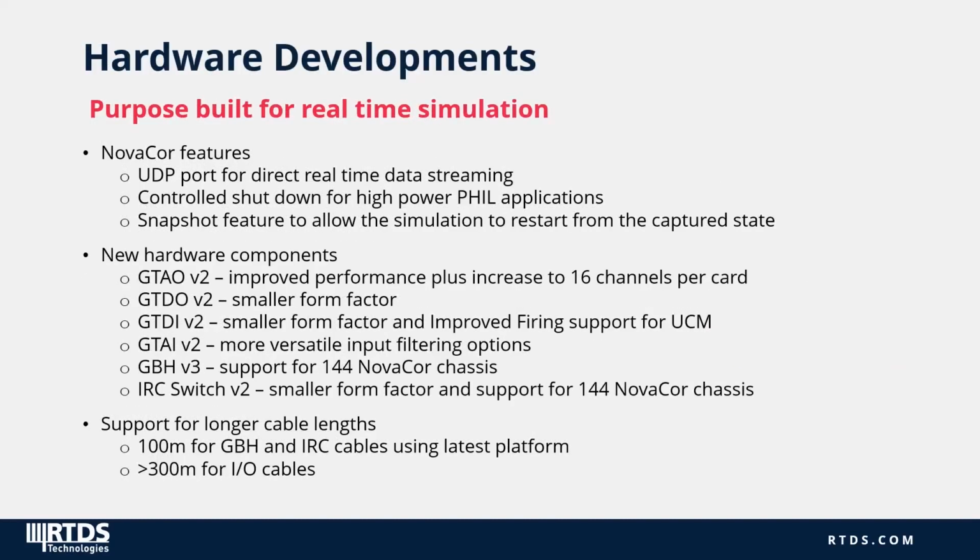Not all of our new developments have been focused on software. We have also made many new developments for the RTDS simulator hardware. On the NovaCore platform, we have added a UDP port for real-time Ethernet-based data streaming. A controlled shutdown feature was added for high-power PHIL applications, and we implemented a snapshot so that you can restart a simulation from any captured point in time.